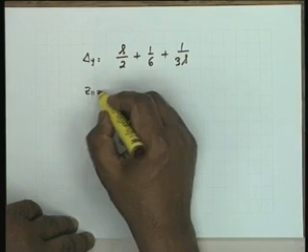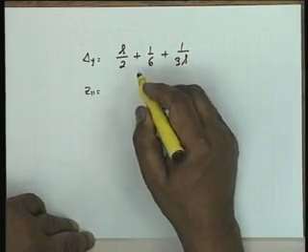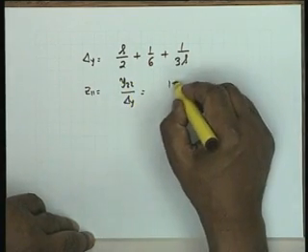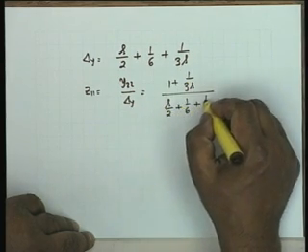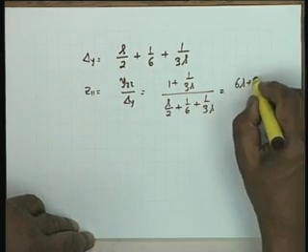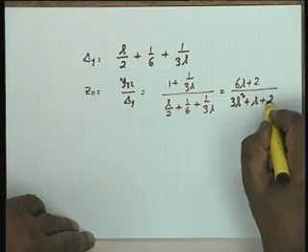If you simplify this, del Y is equal to S by 2 plus 1/6 plus 1 over 3S. This is my result. Therefore, I find Z11 as equal to, you must remember this, Y22 by del Y. So, it is equal to 1 plus 1 over 3S divided by S by 2 plus 1/6 plus 1 over 3S, and this simplifies to 6S plus 2 divided by 3S squared plus S plus 2. I hope I am right.